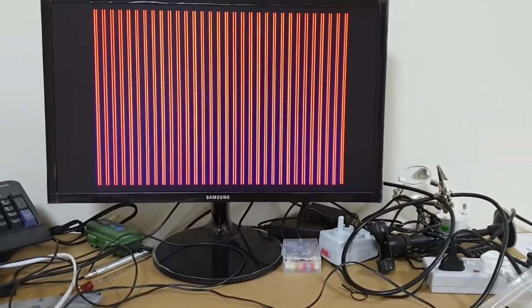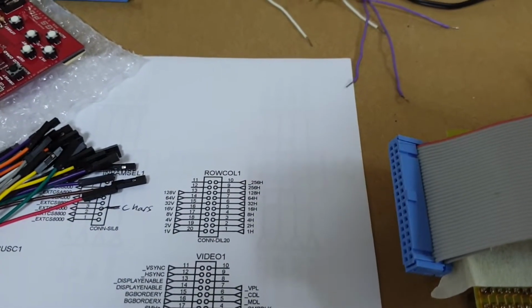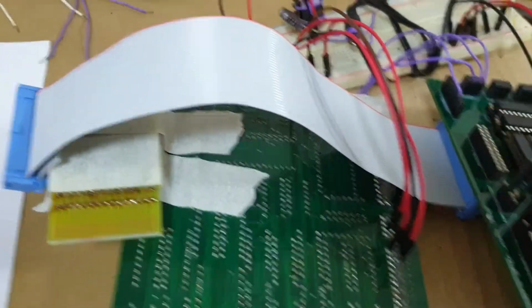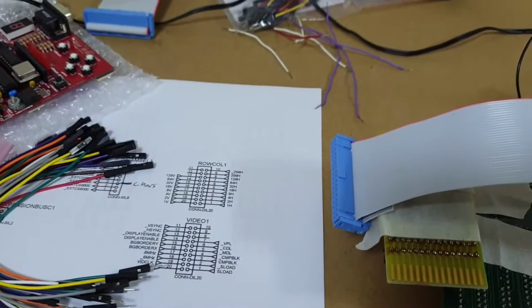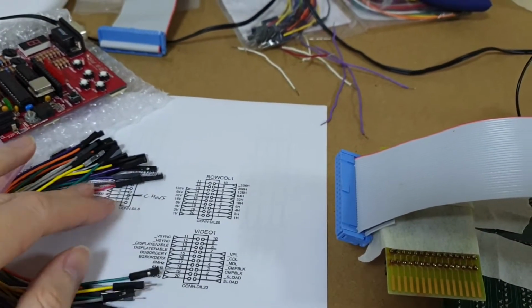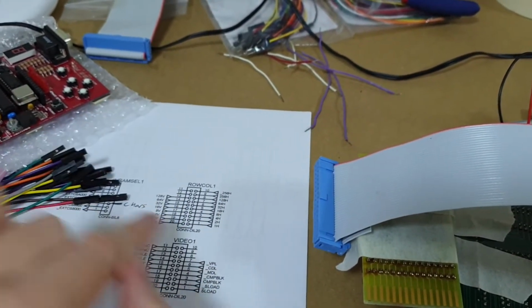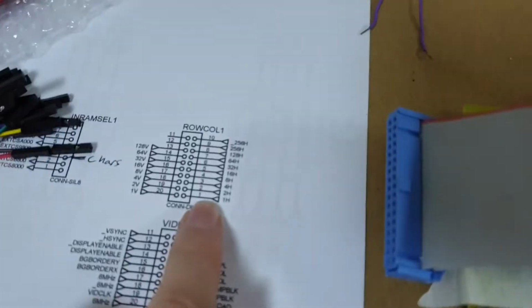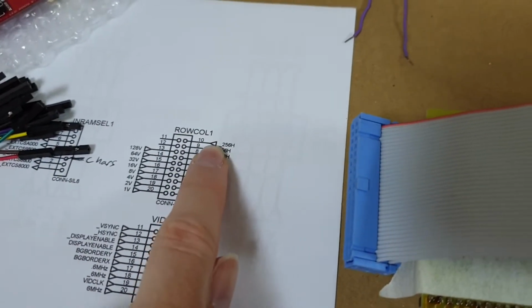This is worthy of note. So basically, this tells me that I'm seeing some really strange signal crosstalk issues, potentially, with a long cable, whereas with the short cable, it was all fine and perfect. Wow, I was not expecting anything like that at all. So the frequency ranges are quite wide and varying. This is 6 megahertz. 1H changes at 6 megahertz rate, and then it divides down as you would expect.